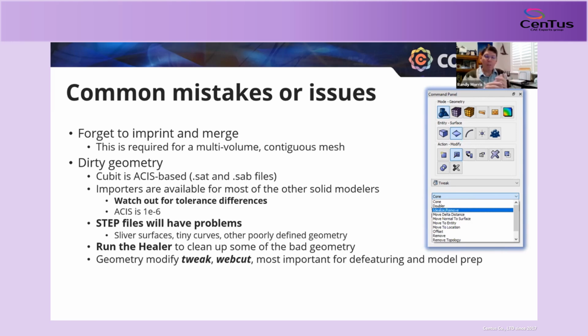STEP files can be extremely dirty, right? Other files are dirty. So we recommend healing the geometry when you import it, especially if it's not a native ACIS file. And again, the tweak and webcut commands are probably the most commonly used for defeaturing and for preparing the model for hex meshing.